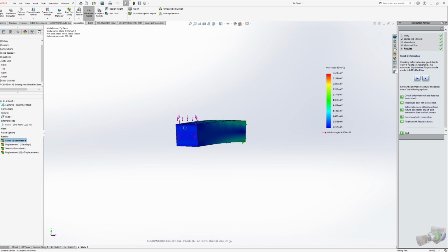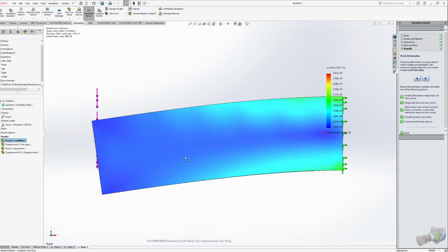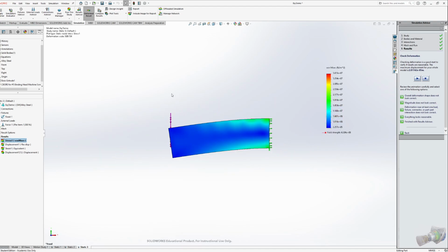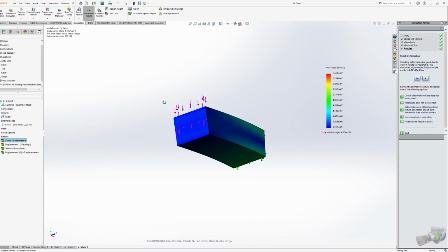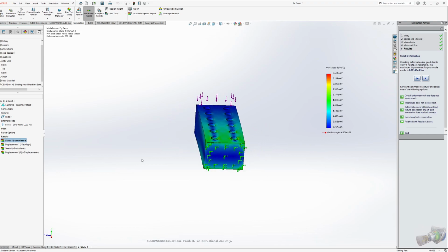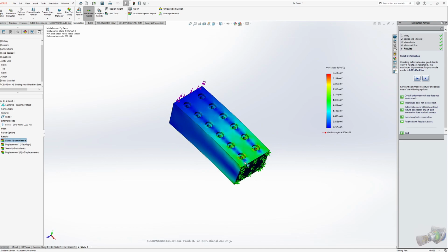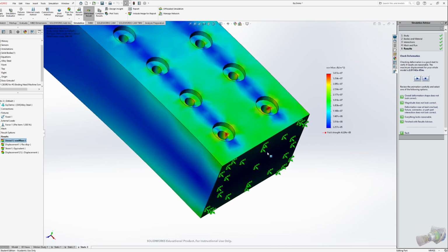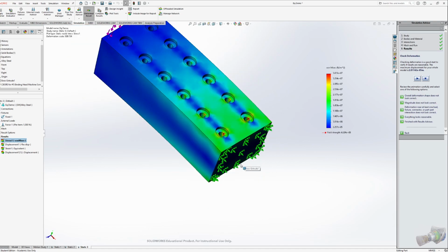So kind of like what you would expect, we're going to get something that is more like a cantilever now. We have some sort of load that is being applied at the very end of this geometry, and not much stress is really going to occur at the very end here, where that shear force was, but we are going to get more stress at regions closer to the fixed region.